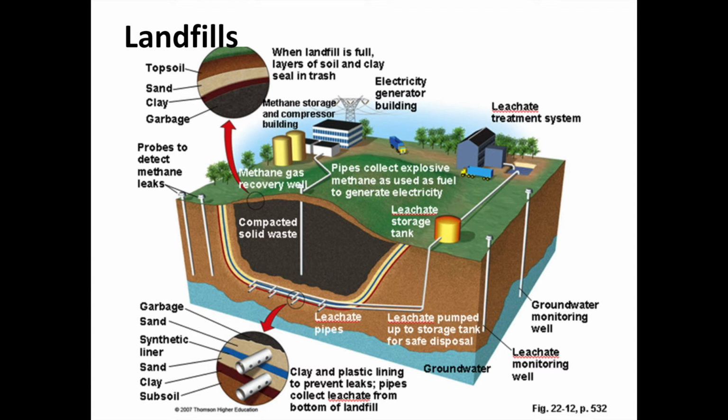Essentially, you need to make sure that the landfill is capped when you're done, or layered with things like clay and sand so that the garbage won't fly away. The bottom of the landfill, the underground part, needs to be sealed so that you don't have leachate just entering the groundwater very easily, but rather have a collection system of piping that collects that leachate and will send it to some sort of treatment facility, whether it's on the grounds of that particular landfill or a nearby wastewater treatment facility. Essentially, we want to make sure we're collecting any of the water that leaches out of the landfill and treat it before it ends up in our groundwater.